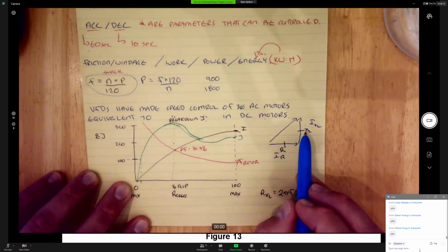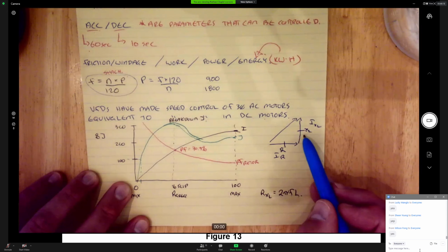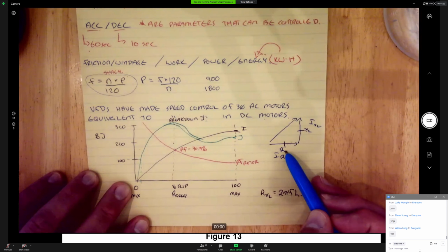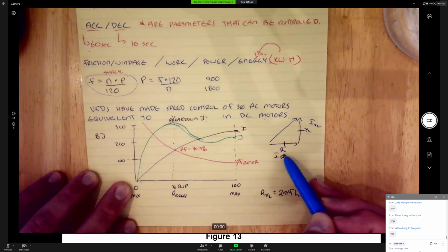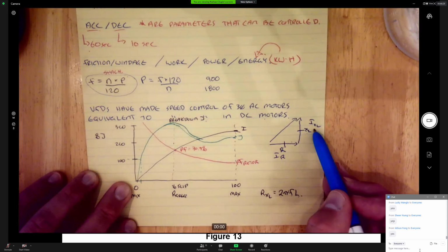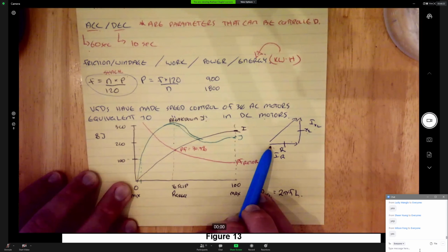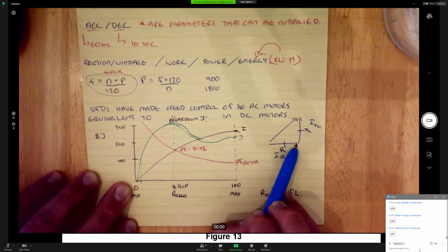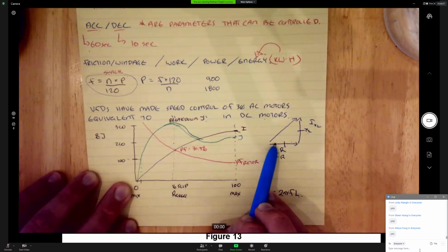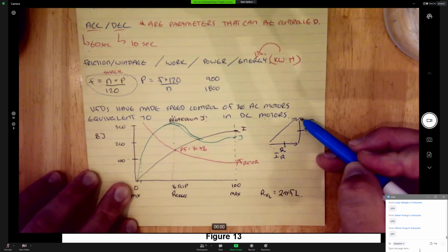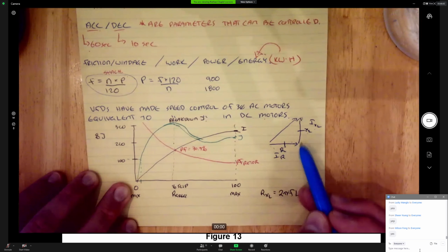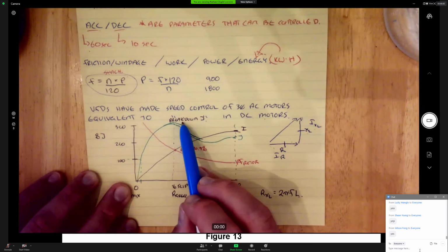And these occur at different times. You should know that that's the whole idea behind representing these triangles and having resistance and inductive reactance: the current caused by resistance and the current caused by inductive reactance occur at different times. So this causes a current, which causes a torque and a push in the rotor at a certain time to start, and right when this one ends, this one picks up and continues. And that is what causes this maximum amount of torque right here.